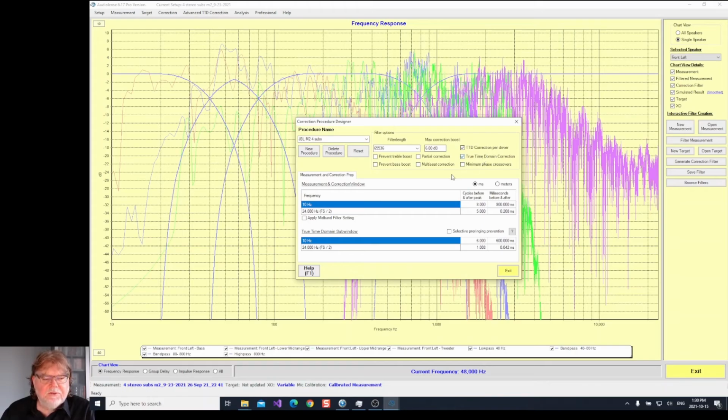Here's what's going to happen. First, we extract the psychoacoustic frequency responses, and we'll show those. They'll show up as smooth responses. Then we correct each psychoacoustic response towards the desired frequency response defined by the crossover and the driver. The driver is treated like a minimum phase system, so we're extracting the minimum phase here. Then we time align all individually corrected drivers, add up the individual simulated responses after per driver correction, and we get one global simulation for the speaker.